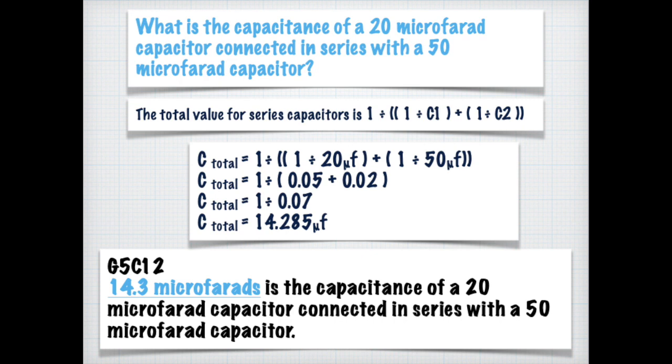So when we plug in the values and do the math, we end up with 14.285 microfarads. But then for the exam, you could just simply remember that 14.3 microfarads is the capacitance of a 20 microfarad capacitor connected in series with a 50 microfarad capacitor.